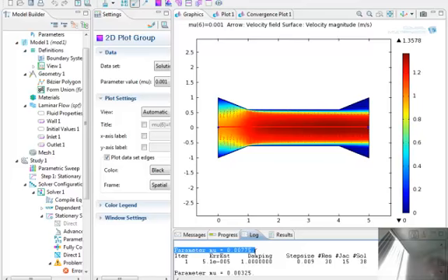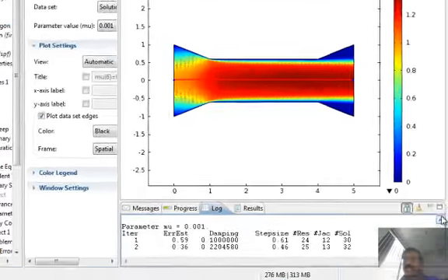If it's not able to get below that, it'll abandon and it'll put up that error message. And if you look at all the previous ones, like here, 0.001, it could not reduce the error. So it abandoned that and then said, okay, I'm going to try for a slightly larger value of viscosity, which is 0.00325. Okay. And you should actually track the whole thing.